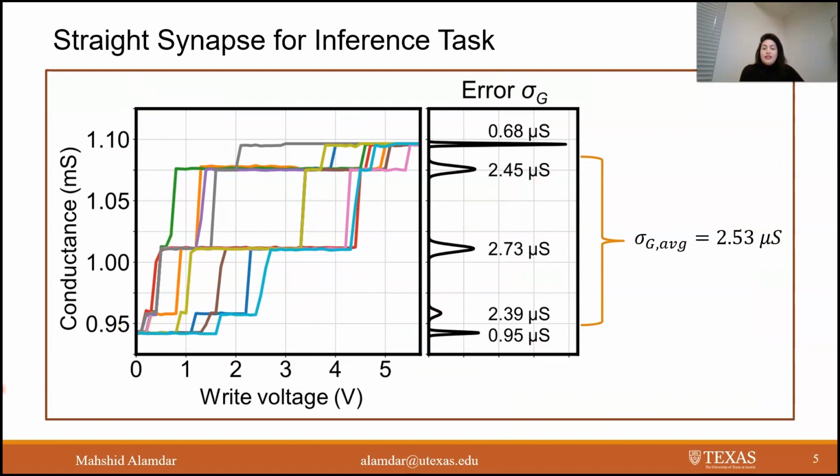Here we simulate an inference task that takes advantage of the high stability of these synapse resistance levels and is not very affected by the randomness observed in setting the levels. To use the domain wall MTJ for a neural net inference application, the MTJ is programmed to the desired weight levels using a write verify process with multiple pulses to overcome the effects of stochasticity. This is a one-time programming operation and is not needed after the system is deployed for the inference application.